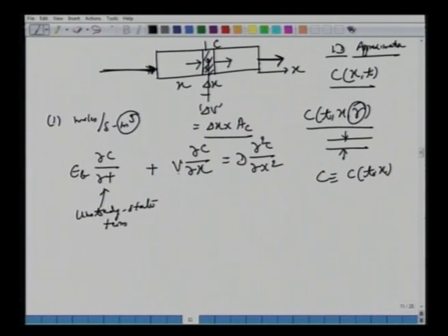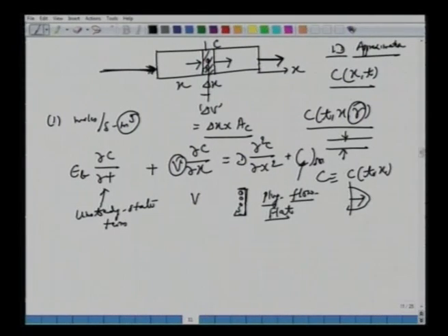So let's say that v is a constant. We have a velocity profile which is more like a plug flow. All right. In an empty tube we would expect a laminar profile. But with a solid packing, it's a very good assumption that the velocity profile is flat here. So v del c by del x, notice there is no r term here, plus or minus there should be one more term here, that's a term of source or sink.